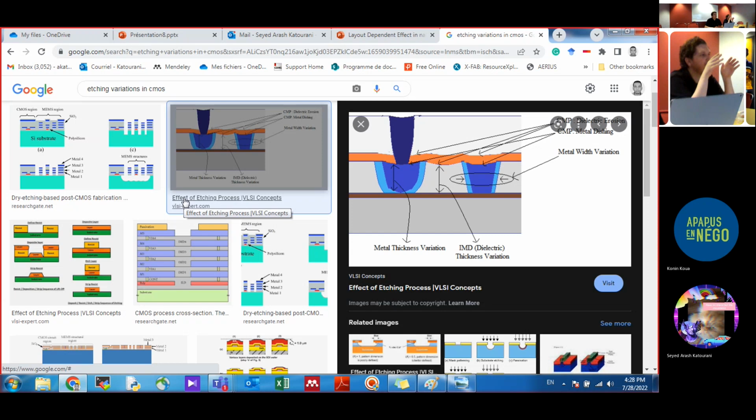So do you want to have your metal further apart to be sure that you always have something uniform everywhere? It doesn't matter, but if your matching is important, you need even the surrounding to see the same. If you have an array of capacitors, with dummies they see the same, because for example the one on the edge will be more exposed than the one in the center.